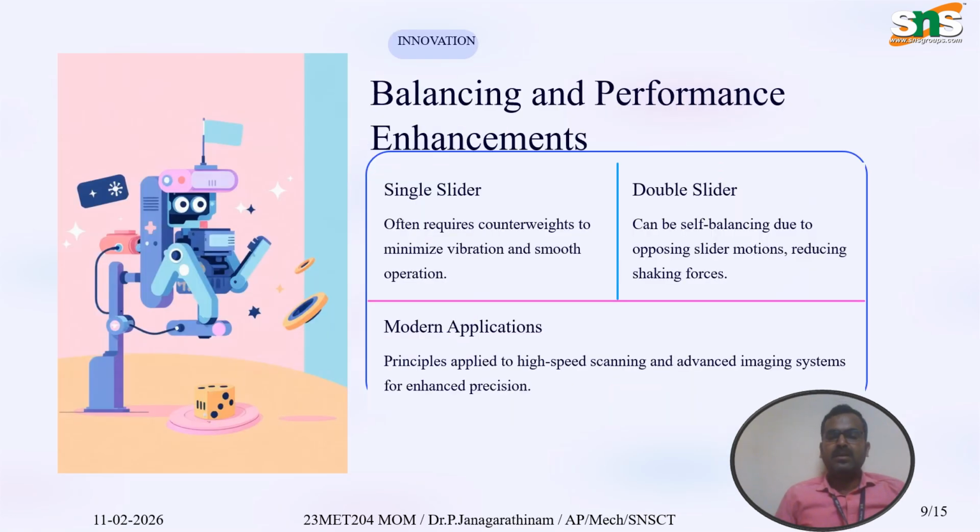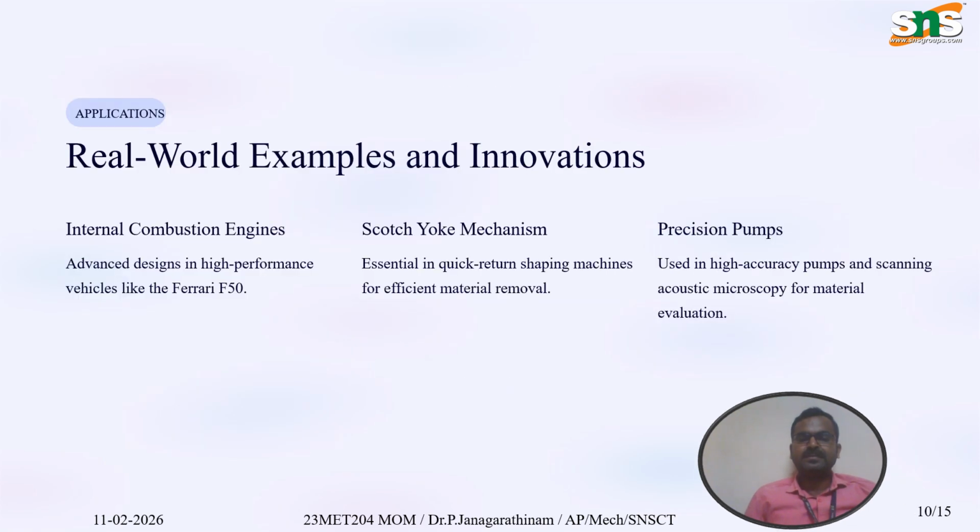On balancing and performance enhancement, the single slider often requires counterweights to minimize vibration and to give smooth operation, when compared to the double slider crank mechanism. As for modern applications, wherever we use high-speed applications, we have to use this kind of slider mechanism.